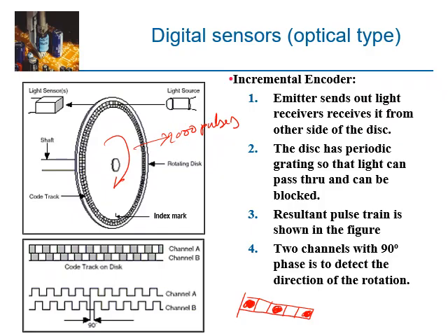So the controller will forget the previous position of the motor, and it will start from the current position as a zero, and it will start to count the pulses, and refer to this current position and get the subsequent positions. So this is a problem.